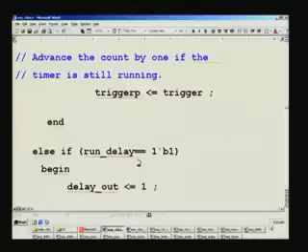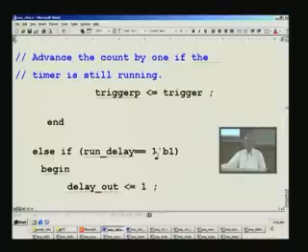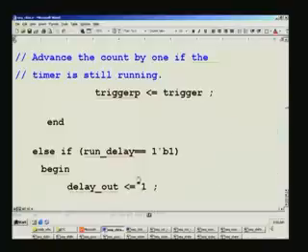This will happen only one time, when previous value is 0 and present value is 1 for the trigger. So subsequent thing, previous value will become automatically 1, because next clock it will be updated. So this will be encountered only at the very first rising edge, right. And if that happens, this is already 1 from that assign statement, and under that condition only this will be made 1.